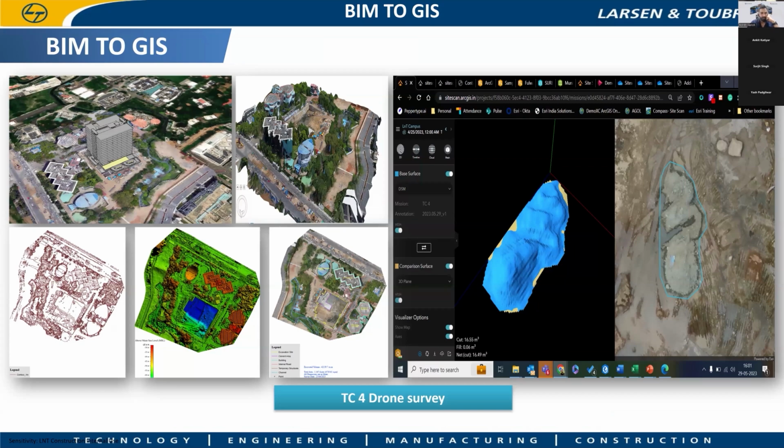Nice. Yeah. And we are also doing some laser scanning, again coming to the SX12, in one of the recent projects where materials are dumped at site. To ensure the volume of the material, we do the laser scanning, and that gives the output of the total volume of the material. We validate through the SX12 whether it matches our requirement and the procurement.